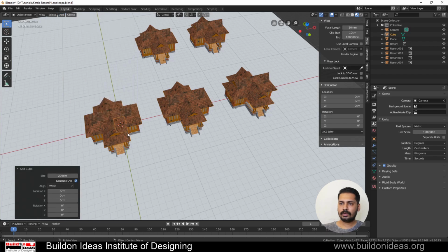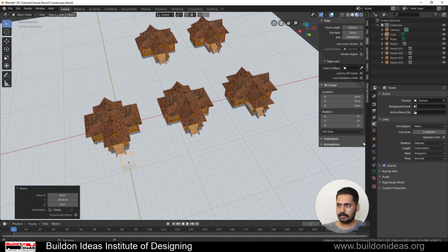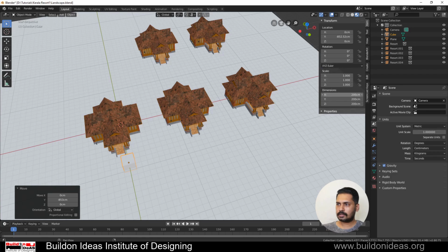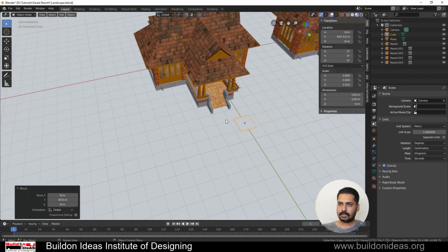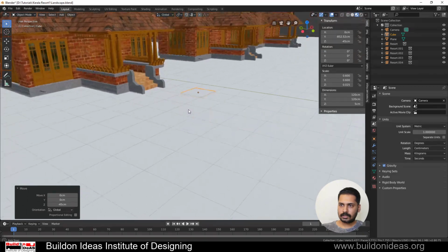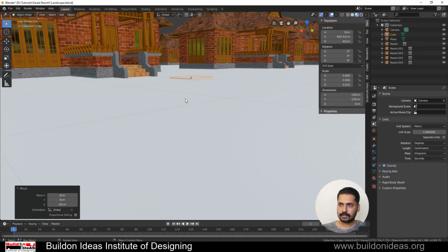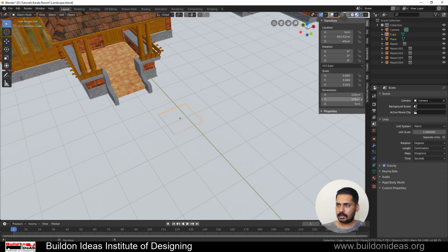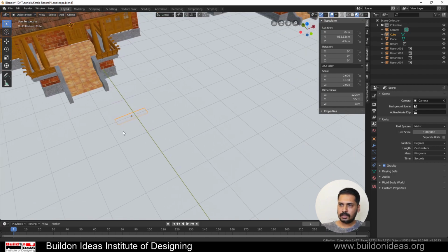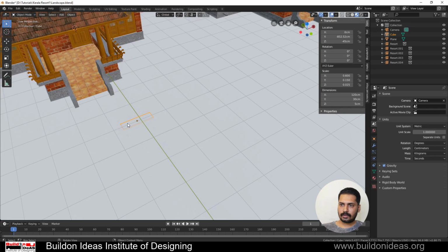In order to do that, we'll add a cube, and then just grab it in Y direction and keep it here, and then I'll go to the items in this, and then I'll make the dimensions 120 by 120 by, say, 5 centimeters. And then I'll move it in Z direction by -45. So that is there on top of this. I'll have to make this by 30. So this is basically a box.